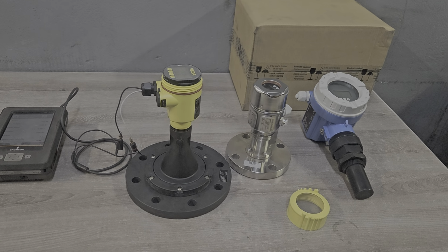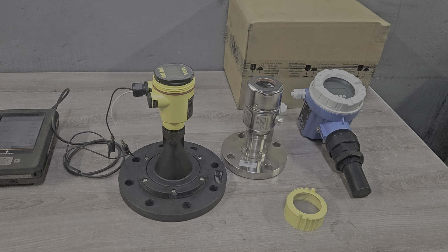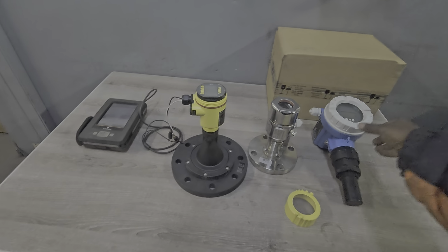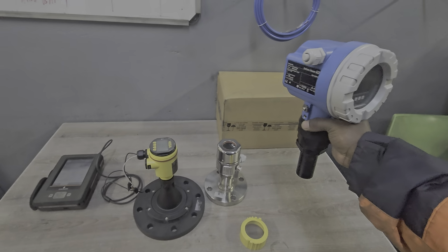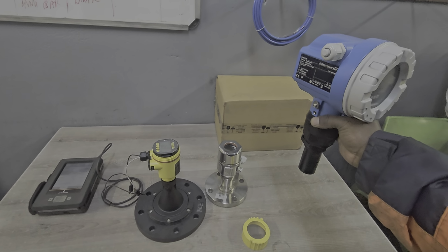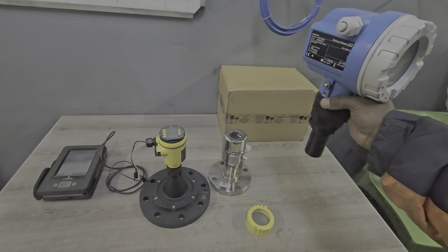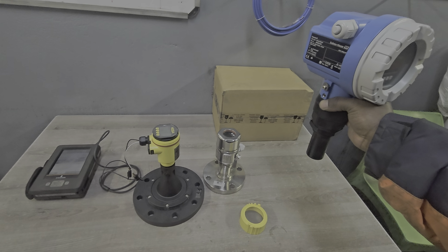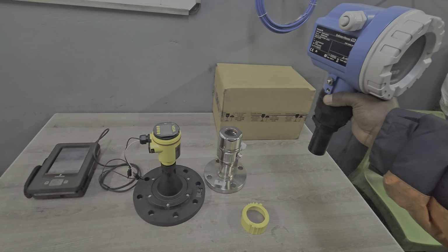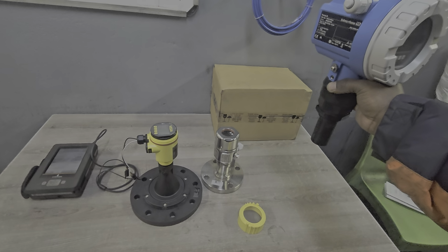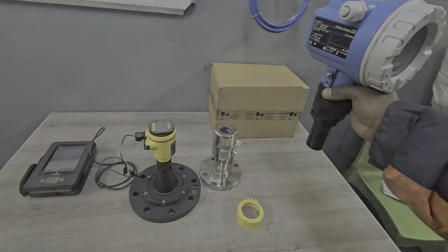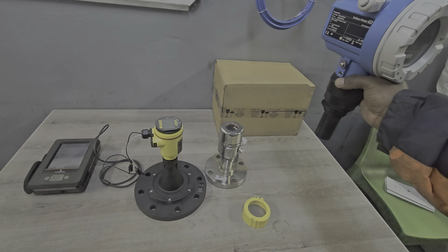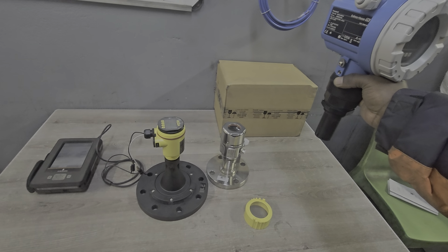With the ultrasonic, it's a sound wave that travels. Again, let me just try to zoom out a bit. So if I take this instrument, put it here, power it up and install it on top of a vessel, it's going to continuously send and receive sound waves. The time it takes for those sound waves to travel from the instrument to hitting the object, let's say my process medium, which is the water or whatever product I'm trying to measure, depends on how far.